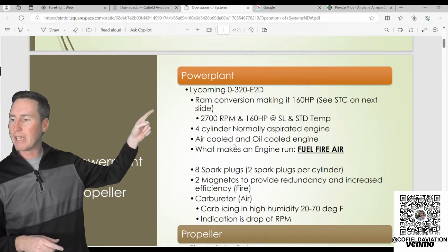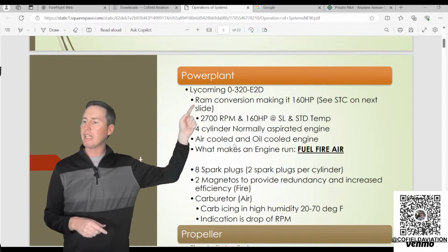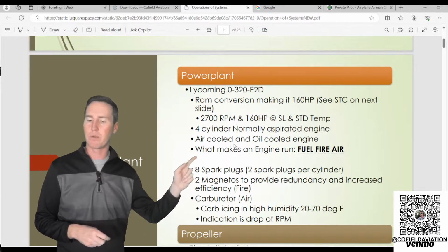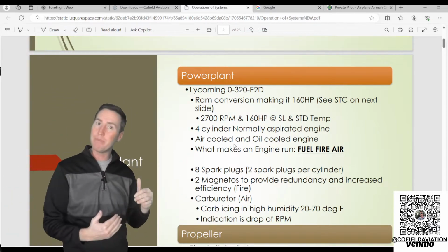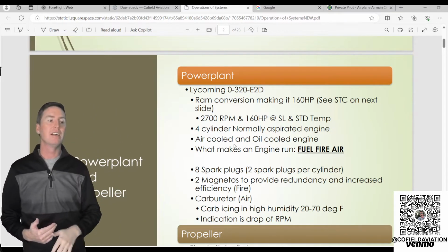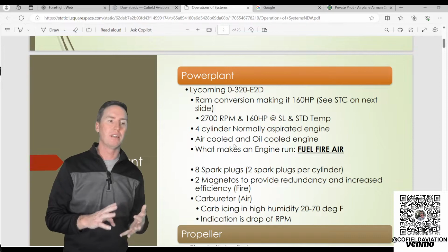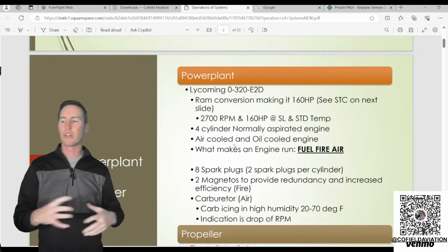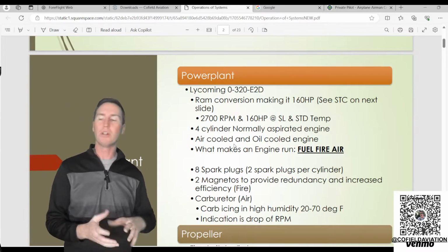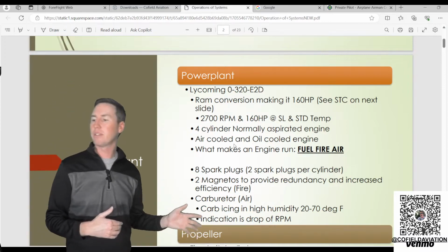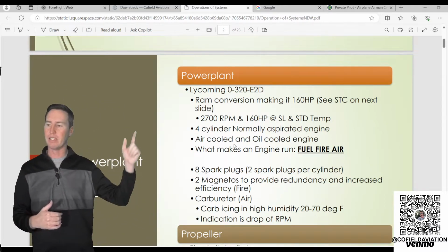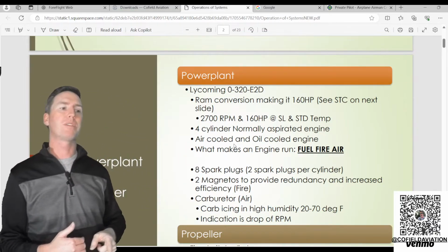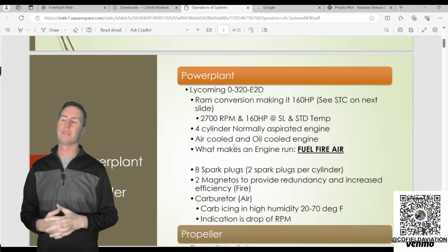But we're going to start off again with the 172 Mike model that we fly. The power plant is a Lycoming O-320-E2D engine. If you remember us talking in airworthiness requirements, we looked up the type certificate data sheet, and that explains exactly what engine we have in the airplane, limitations, weight limitations, fuel limitations, center of gravity, and all that. It's a great treasure trove of information. We'll look at that at the end of this for the 172 Mike model. Basically, this can come out of the type certificate data sheet from the FAA's website, and then of course your AFM, your flight manual, right out of that.